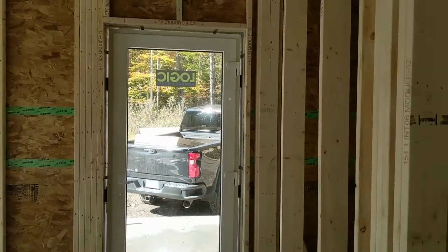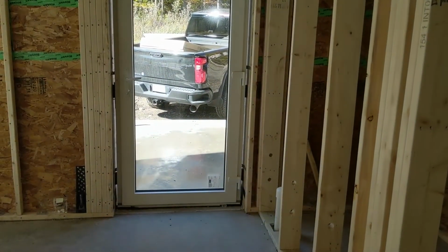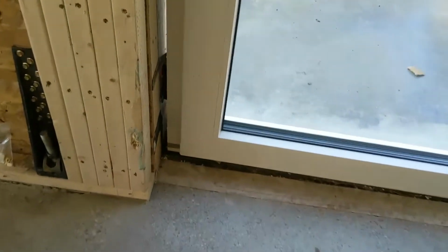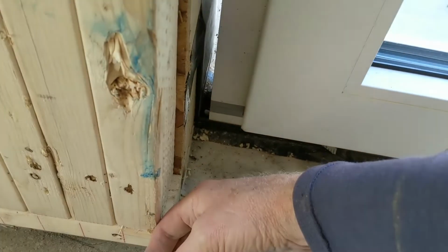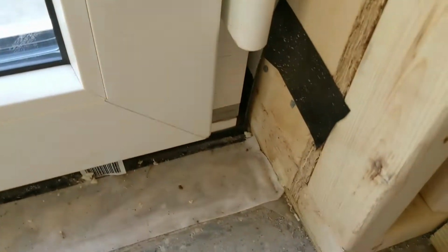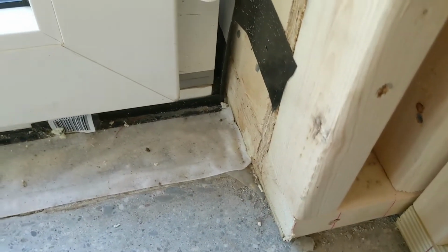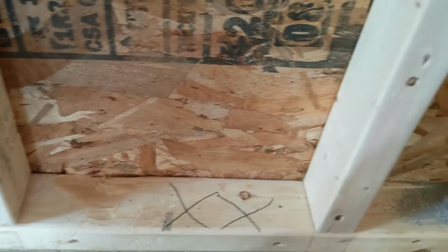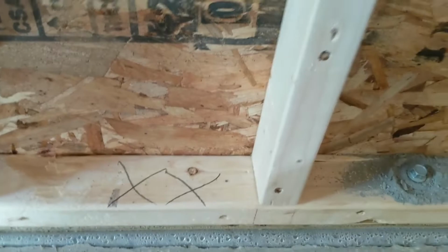All right, I've basically been through the whole house. Didn't find much for air leakage. The only significant air leakage that I could feel was right down here, coming in at each corner of the door. I'm not seeing daylight, but that's a tricky spot, and I'll put some tape on there. I thought I might have felt a little bit here where I've marked it. No, there's nothing there. I must have been imagining it. There's a gasket there, and as long as the gasket's continuous, we're good.